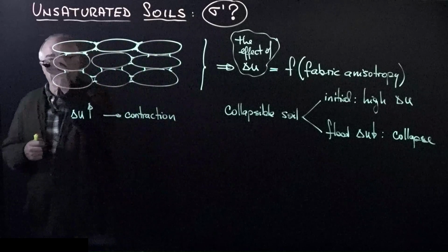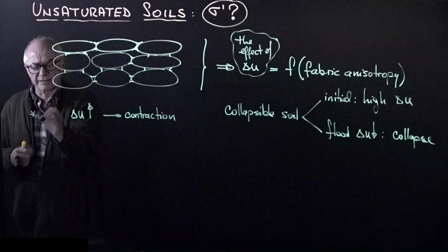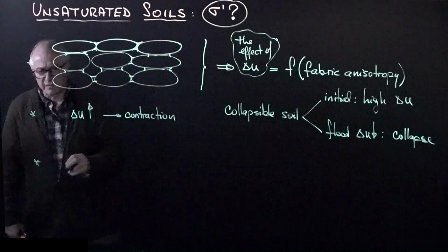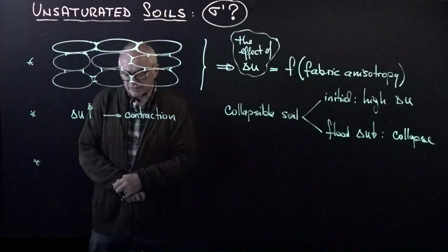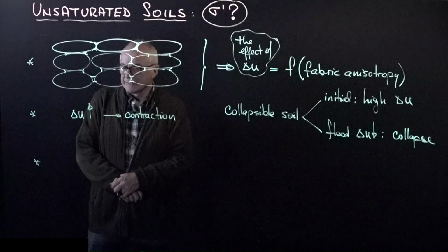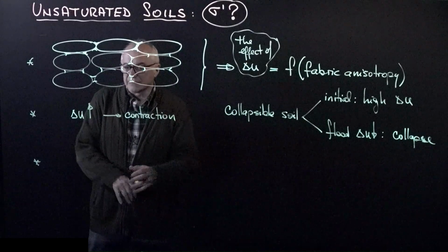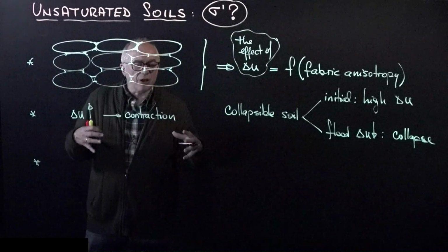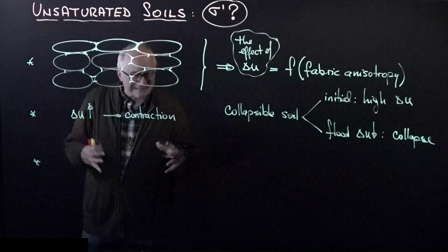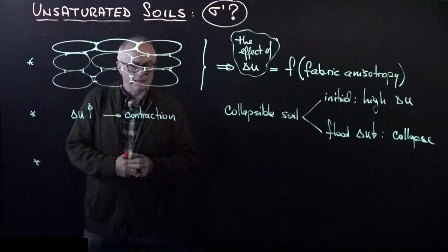This was recognized, in fact, by Bishop and others early in the 1960s, and by that time, Fredlund and Morgenstern, among others, were beginning to say that probably we shouldn't combine the boundary stress with the effect of forces created internally by suction.